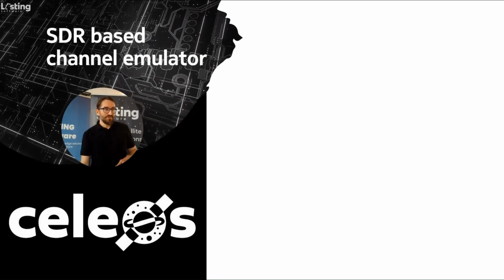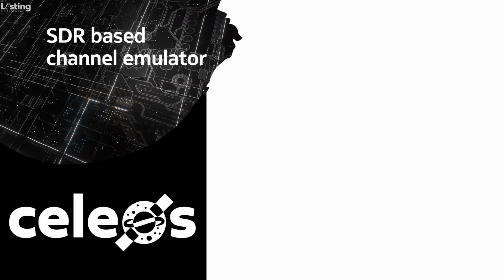How does CELEOS work? The general idea behind the architecture of the channel emulator is to use a software-defined radio to perform analog to digital and digital to analog conversion of RF signals, and off-the-shelf GPUs for processing. The software is designed to be hardware agnostic, being able to function with a range of both SDRs and GPUs. Several configurations can be implemented, varying in terms of hardware, and therefore in the number of supported channels and their bandwidth, but all using the same software.